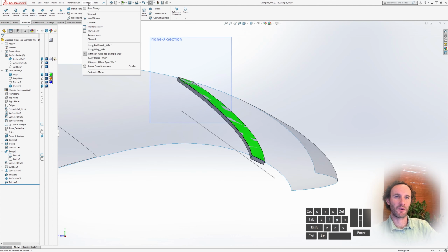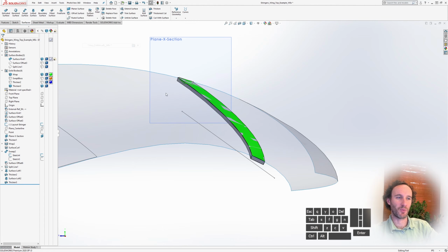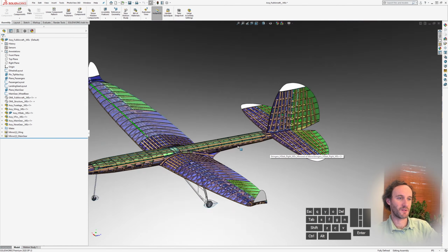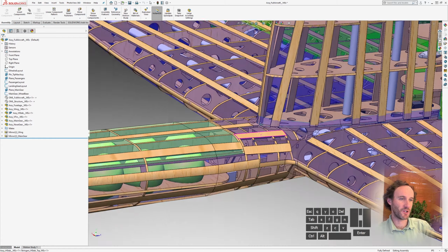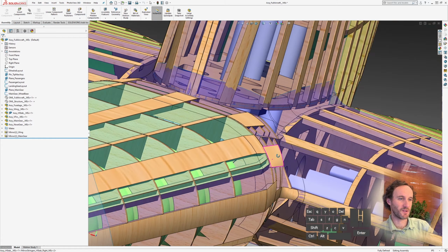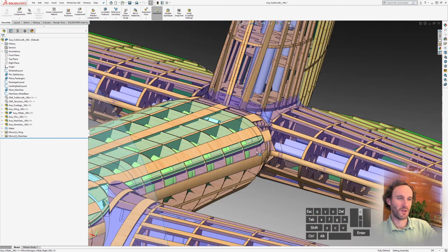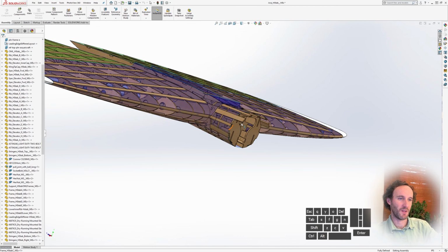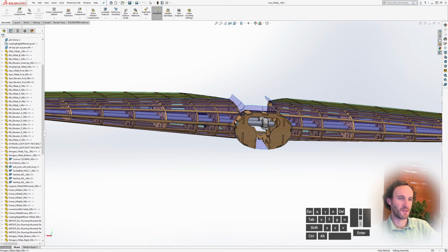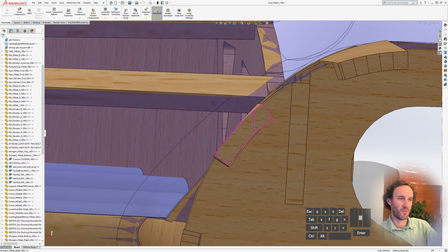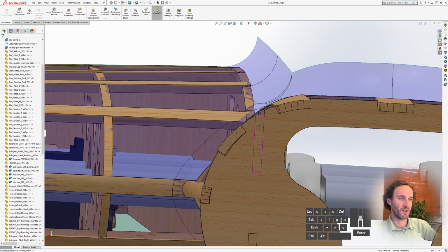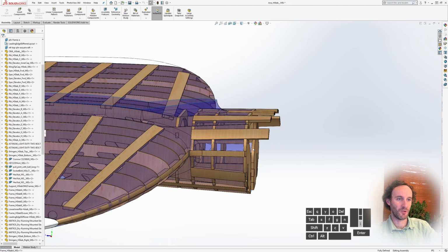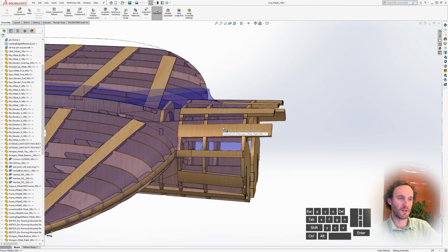There are areas on the aircraft though where you might have to take a different approach. Like for instance, on the aft fuselage here, that curvature is tighter than the wing. So if we take a look at the aft fuselage portion of the H-tab here, we can see that this might be a little too curved for actual use as our cutouts. So that might be a place you might want to use that split line and surface Euclidean offset.